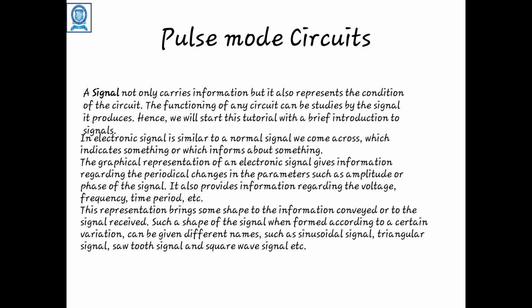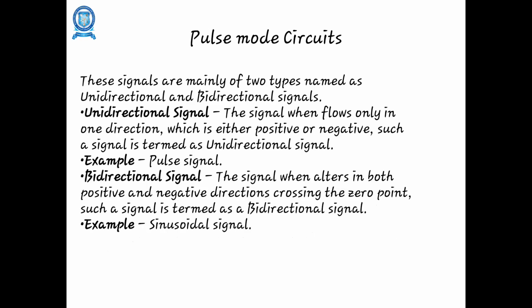But in synchronous sequential circuits, the designer has to consider the time delays involved to determine the maximum operating speed of the clock. So, the designer has to determine the speed of the clock, and that is very important. In asynchronous sequential circuits, the clock is absent and state change occurs according to the delay times. Due to this, asynchronous sequential circuits are more difficult to design.